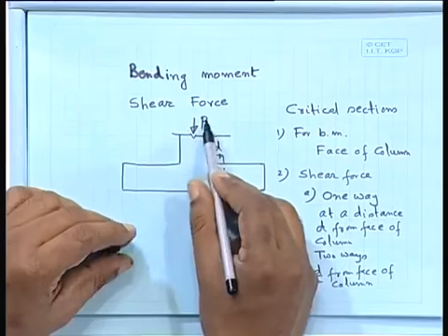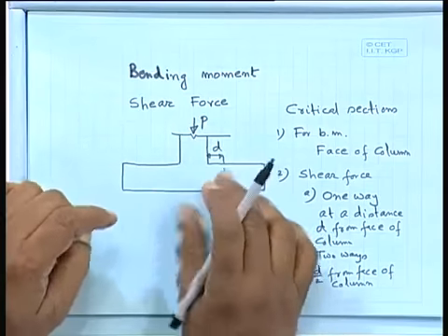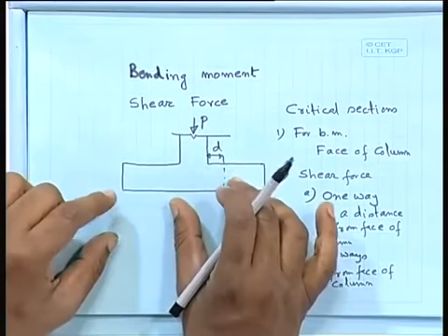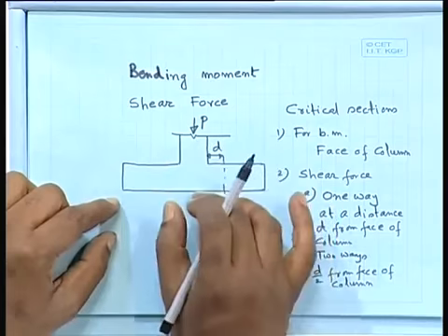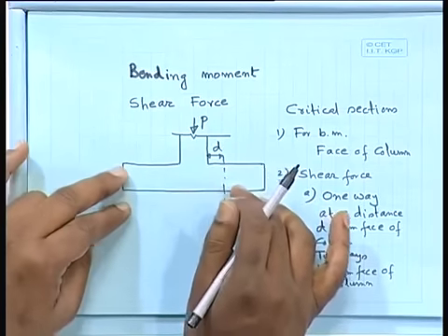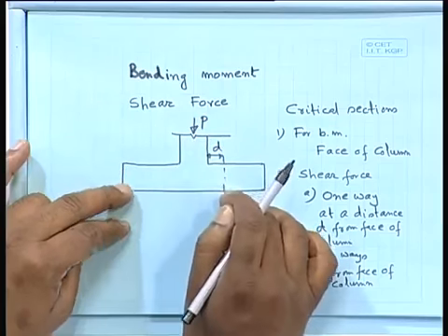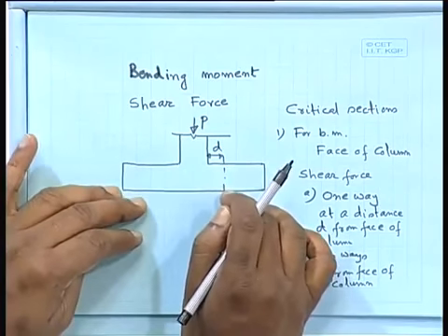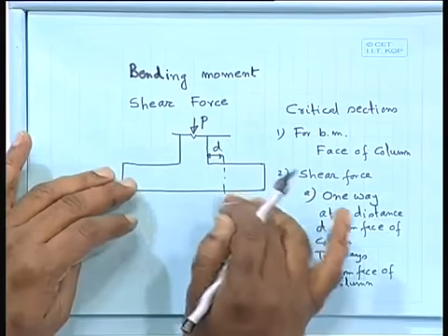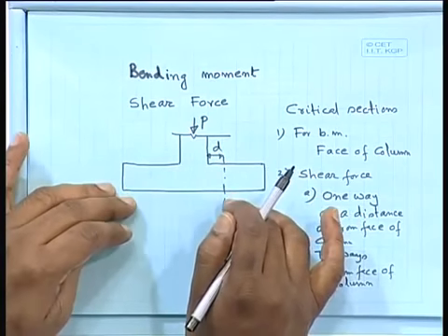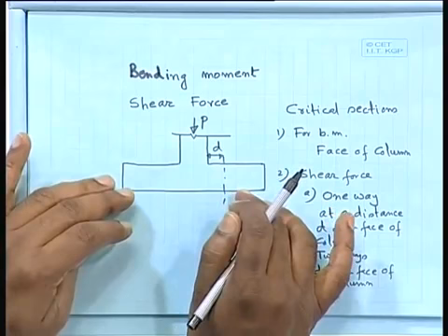So that you should remember. So your column load, and maybe 10% you can take for the footing, because the footing size you have not yet decided. So 10% of the axial load coming, you can take as the self weight of the footing. So considering that, you can find out the footing size under serviceable condition.